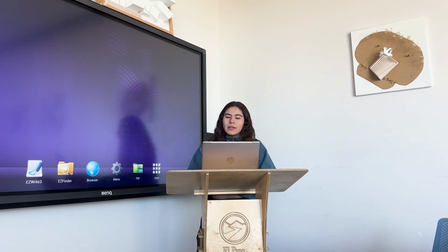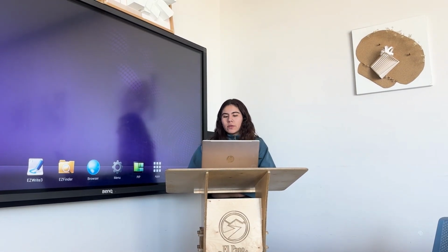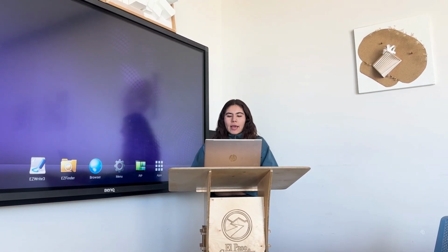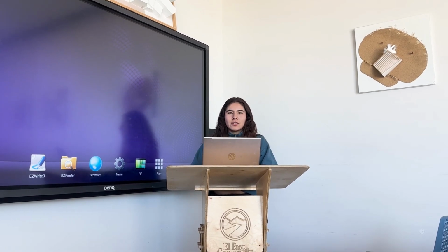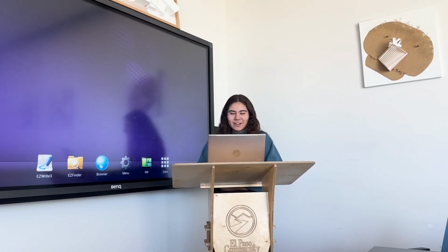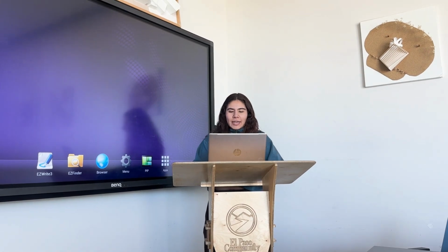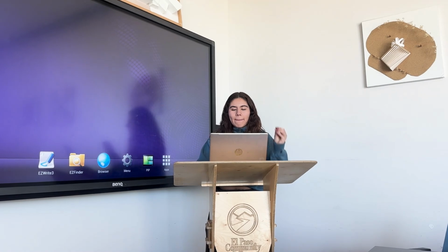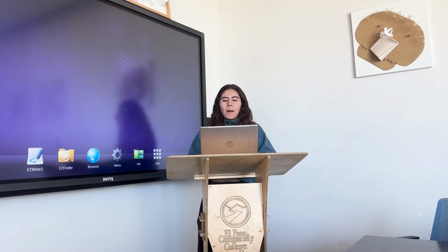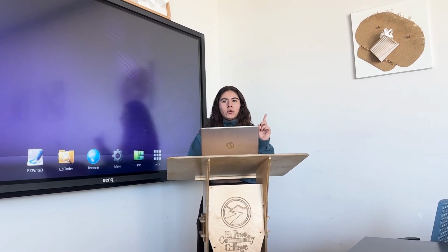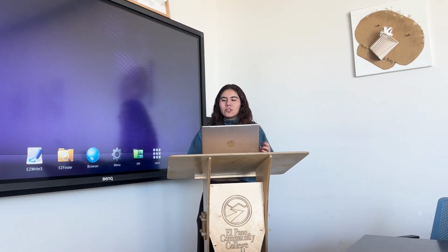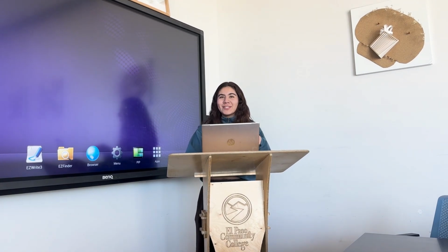So weep holes at the cavity bottom should be spaced not more than 24 inches, 600 millimeters, horizontally in brick, and 32 inches, 800 millimeters in concrete masonry. Weeps should lie immediately on top of the flashing in the wall to keep the bottom of the cavity as dry as possible. These weeps are formed by leaving open head joints between units that make the weep the full width of the joint and at least 2 inches, 50 millimeters tall.